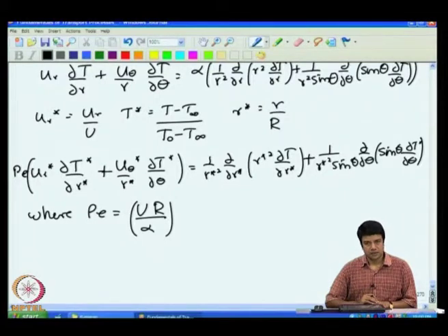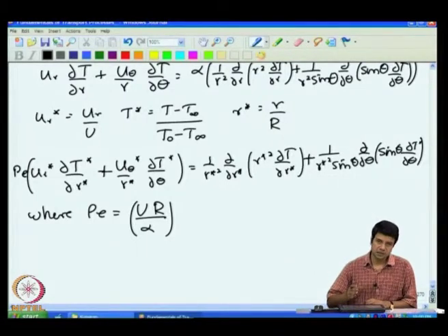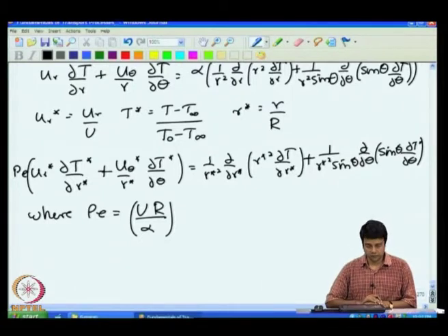As the thickness of the boundary layer becomes small, the gradient becomes large and the diffusion in the direction perpendicular to the surface becomes large. And if the thickness is sufficiently small such that the diffusion term balances the convection term, then one has a balance between convection and diffusion, diffusion perpendicular to the surface and convection in both the flow as well as the gradient directions.